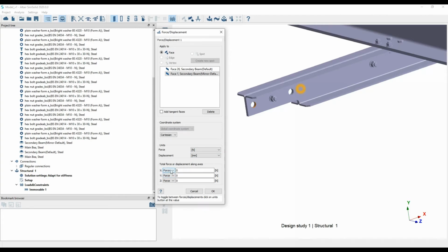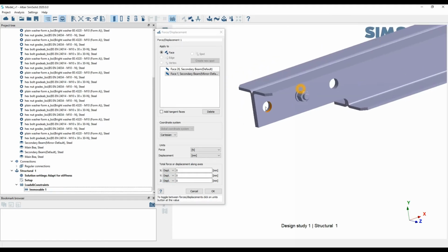And what's nice is that although we had the constraints plane, what you can always do is specify a displacement as well. So if displacement is 0 on all of that, then obviously you're telling it that none of these faces can move. So that's another nice way of implementing constraints or guided movement. So say if we're only letting it move, or there's only a force of minus 1000 newtons in Y.